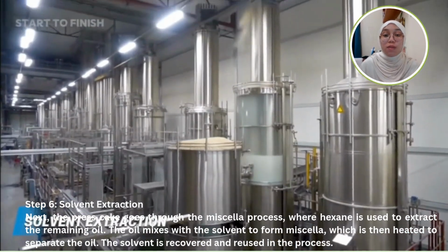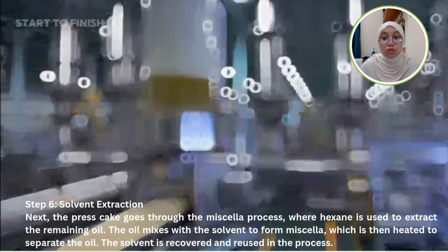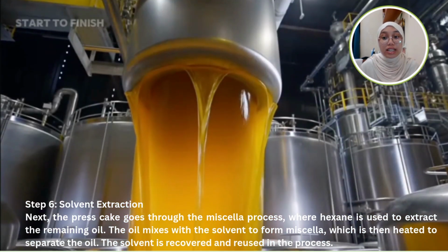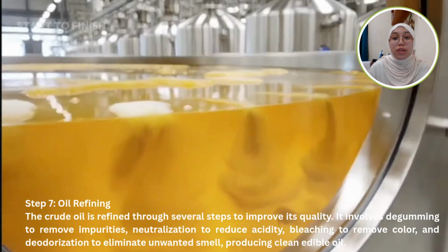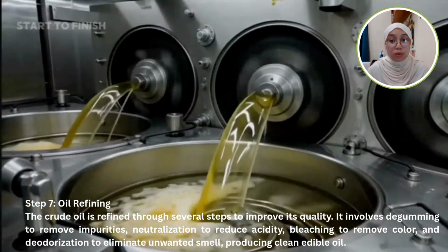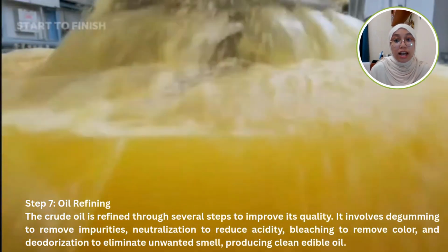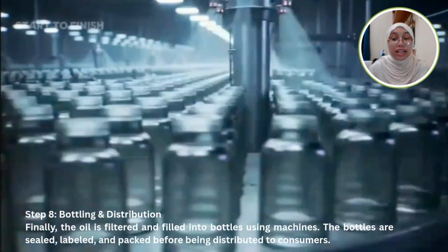Next step, which is solvent extraction. The press cake goes through the micellar process, where hexane is used to extract the remaining oil. The oil mixed with the solvent forms a micella, which is then heated to separate the oil. The solvent is recovered and reused in the process. After that, we go to the next step, which is oil refining. The crude oil is refined through several steps to improve its quality. It involves degumming to remove impurities, neutralization to reduce acidity, bleaching to remove color, and deodorization to eliminate unwanted smell.